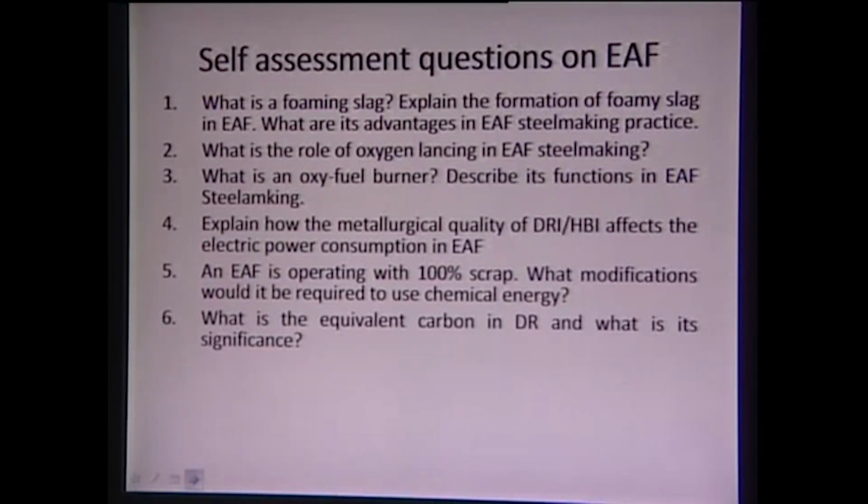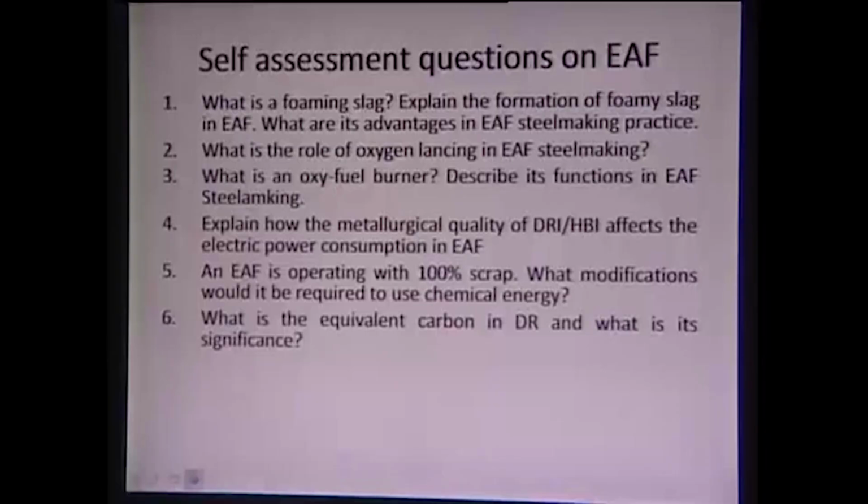I have discussed this, I have calculated some values also. An EAF is operating with 100% scrap. What modifications would be required to use chemical energy? The modification would be either you inject carbon or you inject oxygen, because for utilizing chemical energy you have to have a chemical reaction. What is the equivalent carbon in DRI and what is its significance? Already I have calculated the carbon content in DRI and stoichiometric, all these things you have to bring over here.